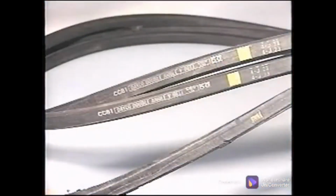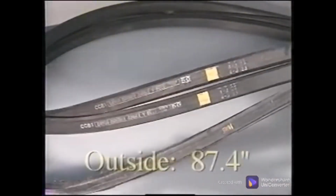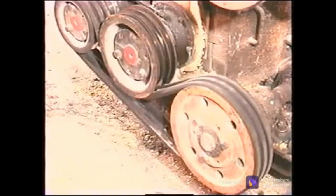These belts are size CC81. The CC refers to a double C size belt, which is measured on the inside. So this belt is 81 inches long on the inside, but is 87.4 inches on the outside. Only one belt is bad, but all 3 must be replaced. The other 2 are worn more than a new belt would be, and it is important to get a matched set, as variances in length affect the efficiency of the drive.